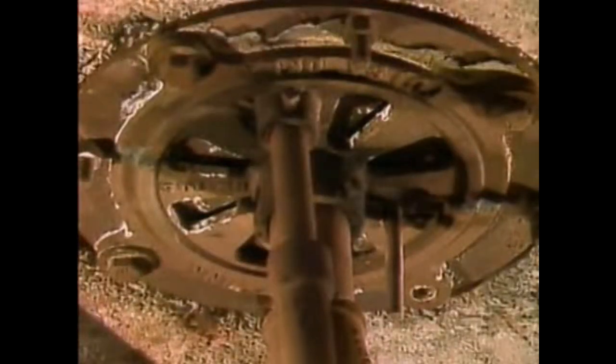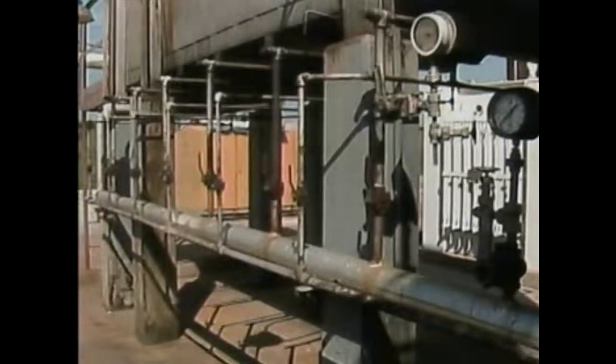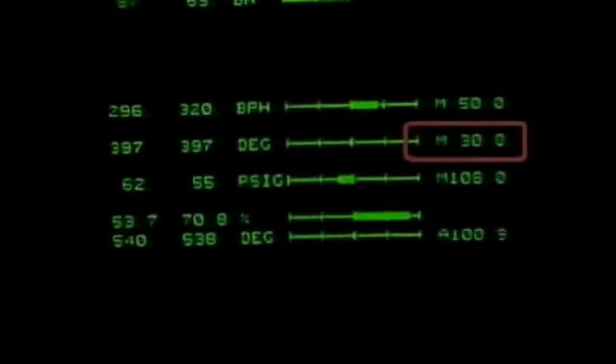In addition to the airflow conditions, the fuel supply to the burners also has to be controlled. If there's too much fuel, some could be wasted because fuel may leave the furnace without being burned. If there's too little fuel, there's a risk of flameouts and explosions.